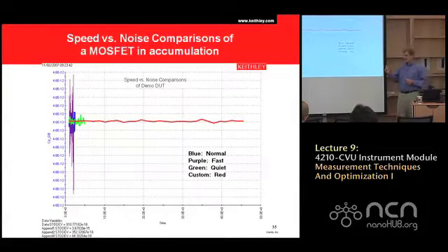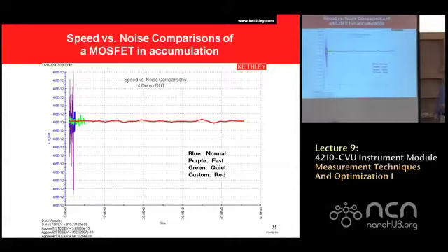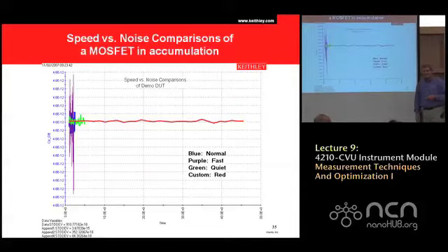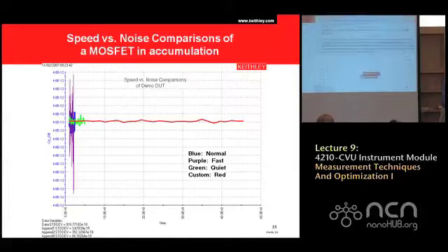All right, this is actually on a MOSFET, on a wafer. This is actually a really big MOSFET, 4.6 picofarads of gate capacitance. And so I just wanted to give an example on an actual wafer of fast, normal, and quiet. And that doesn't have a chart of the noise. So we actually have the standard deviations here.